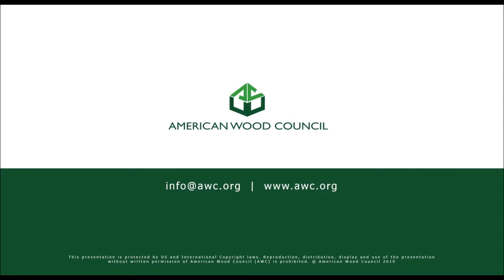Sure. Yeah, unrelated to the Tallwood Building Ad Hoc Committee changes, there was a change in this past cycle, Group A, that would allow the same type of protection for concealed spaces in traditional Type 4 heavy timber as is required for these spaces in mass timber now. And this protection is also mirroring the protection of concealed spaces that's given in NFPA 13, the sprinkler standard itself.